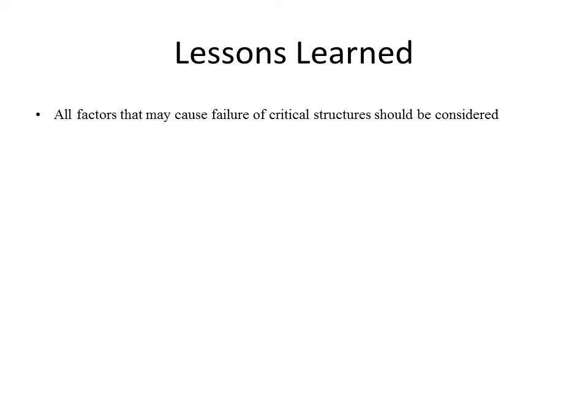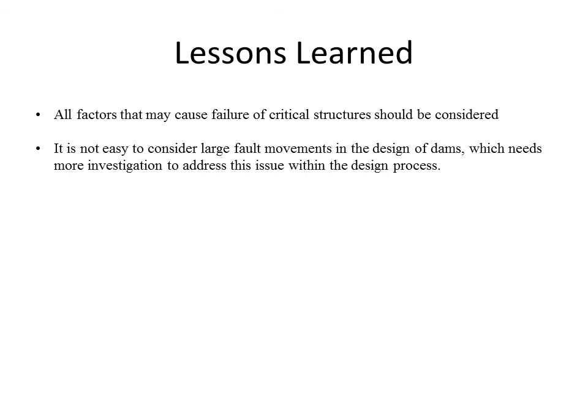Lessons learned from this case history are: all the factors that may cause failure of critical structures should be considered in the design, which was not the case for the Baldwin Hills Reservoir. It's not easy to consider large fault movement in the design of dams, which needs more investigation to address the issue within the design process.